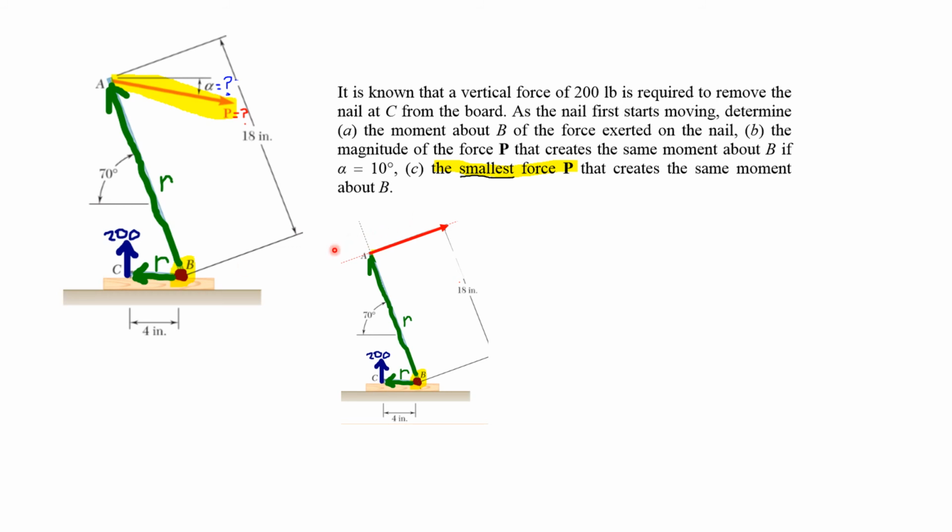If our force is 90 degrees with a lever arm, then 100% of that force is going to do nothing but rotate it. Anything that's not 90 degrees, it's not rotating it. It's just pushing and pulling on it, and it's wasted effort. If the point of all of it is a rotational motion, then we want all of our effort to go straight into rotational motion.